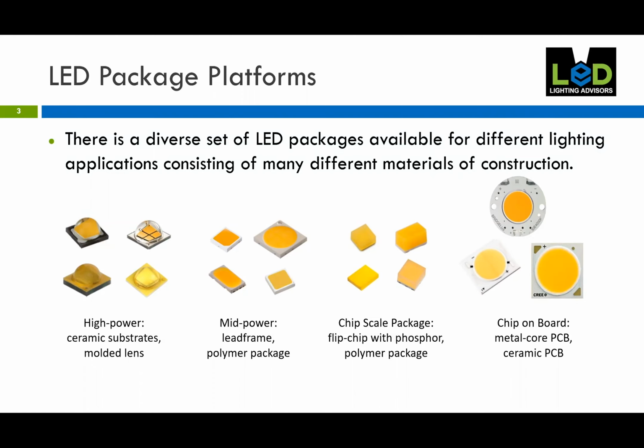And then finally, we have chip on board LEDs, or COBs, which consist of many small LEDs mounted to a metal core PCB or a ceramic substrate. These are covered with a phosphor-containing encapsulant, and this platform is typically used when high luminance is required.